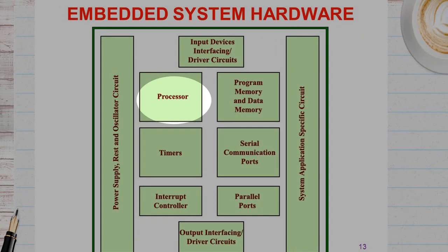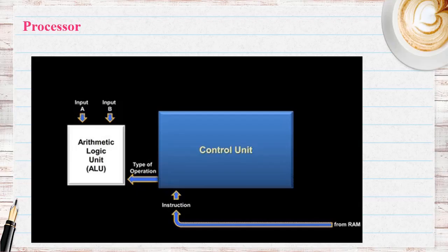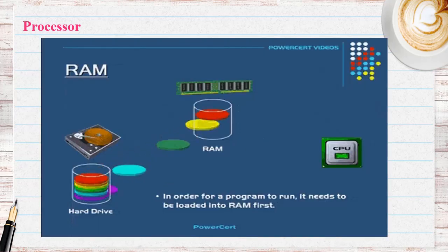Knowledge of the basic concepts of microprocessor and microcontroller is a must for an embedded system designer. A processor has two essential units: the program flow control unit and the execution unit. The control unit includes a fetch unit for fetching instructions from the memory. The execution unit has circuits that implement the instructions pertaining to data transfer operations and data conversion from one form to another.